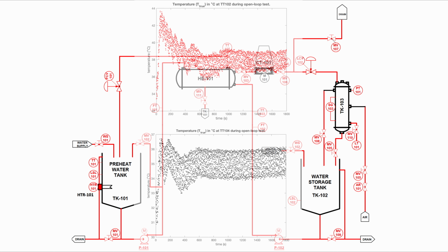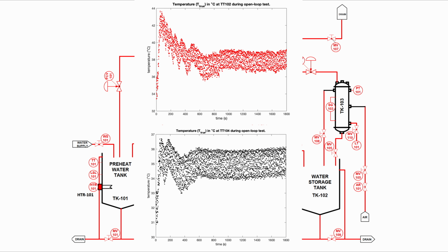We can see from the plot that the open loop test provides useful information about the process dynamics of the temperature system. We are going to use this particular data for a system identification exercise later on. All this useful, informative data is recorded and logged using MATLAB software.